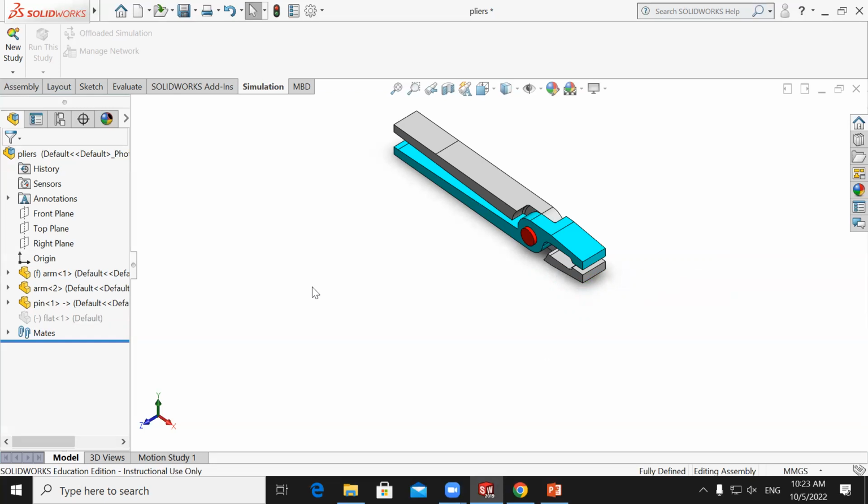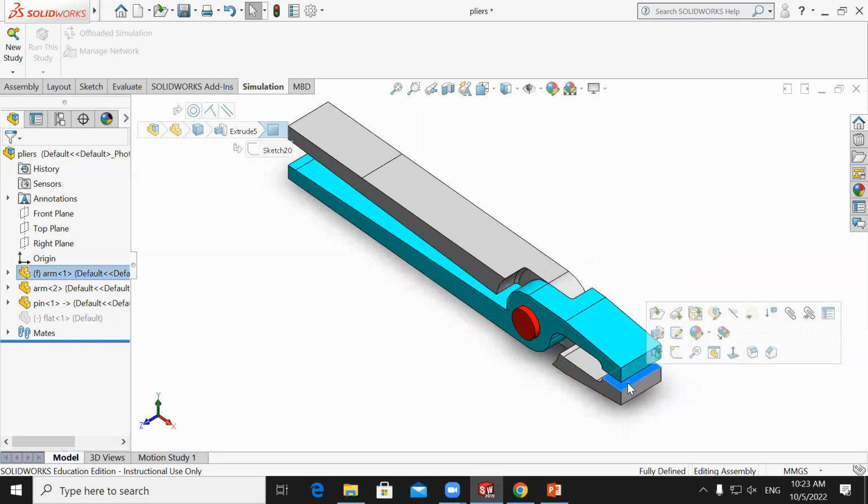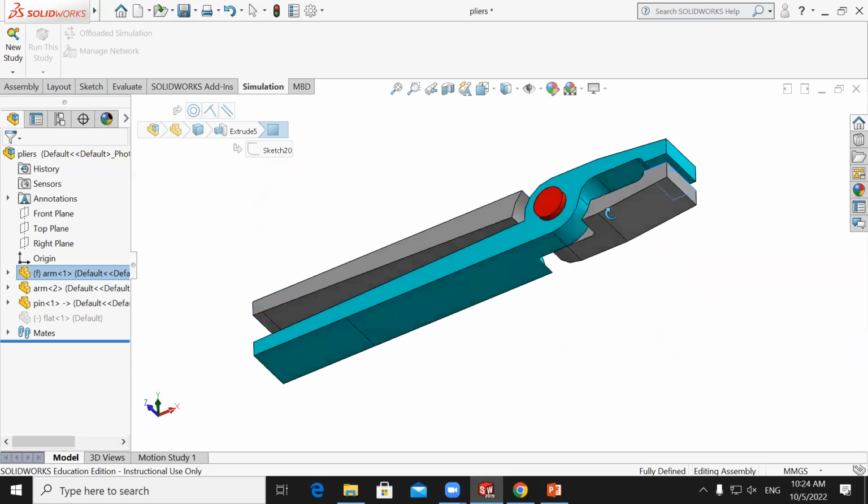Then on the tool's surface, we have to apply a restraint saying that it's fixed, because it's replaced with the flat. We will set that fixed. Also the outer surface here as well should be fixed.